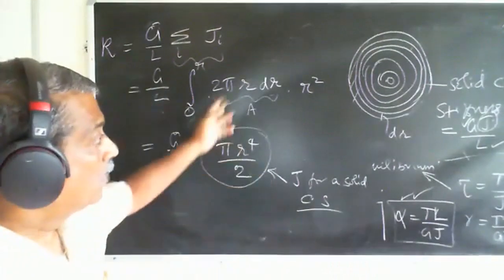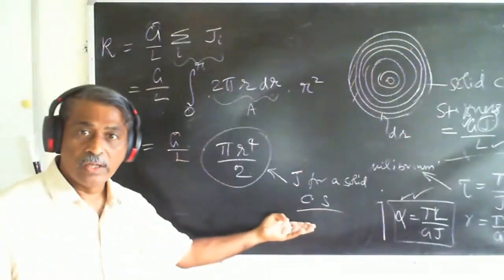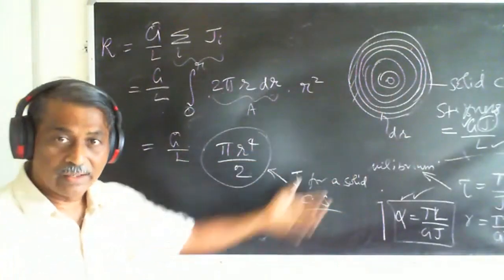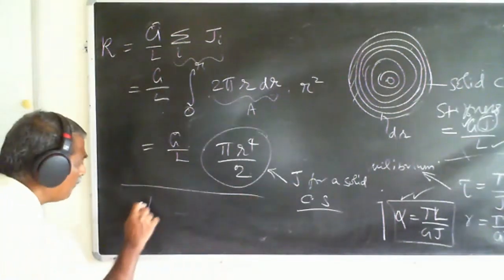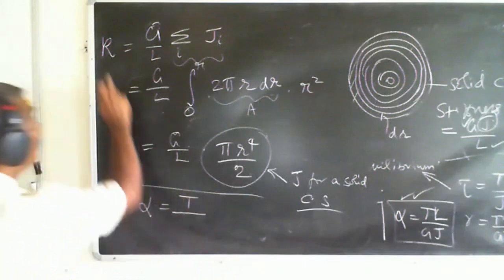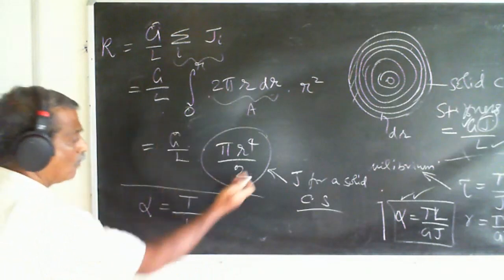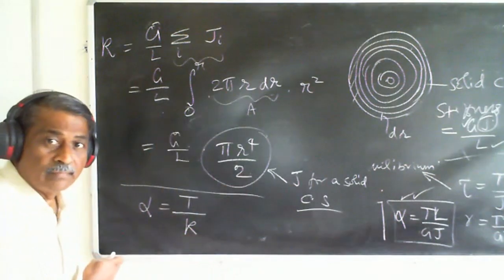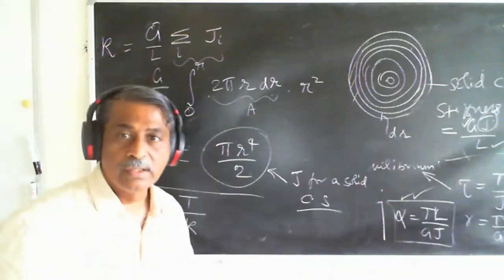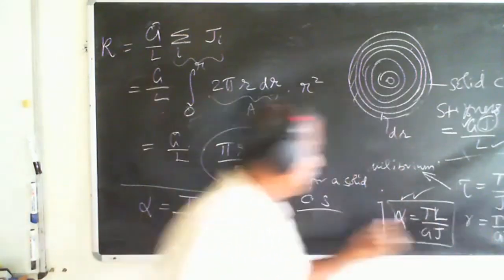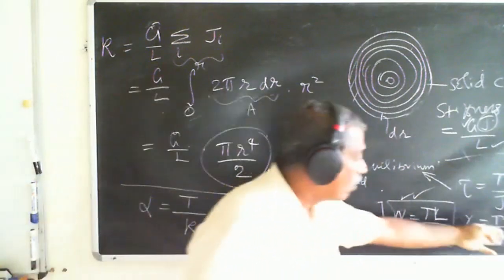So remember we derived for a hollow tube. Now I can find out for a solid cross section by simply integrating, right? All the rest of this formula are the same, right? How do I find out alpha? Alpha is nothing but T by stiffness K, correct? So K I have already found out. I can insert it and get alpha, right? From alpha, it is possible for me to get all the other terms that we are looking at here. Here, if I substitute for this J instead of the other J, I should get all the results over here.